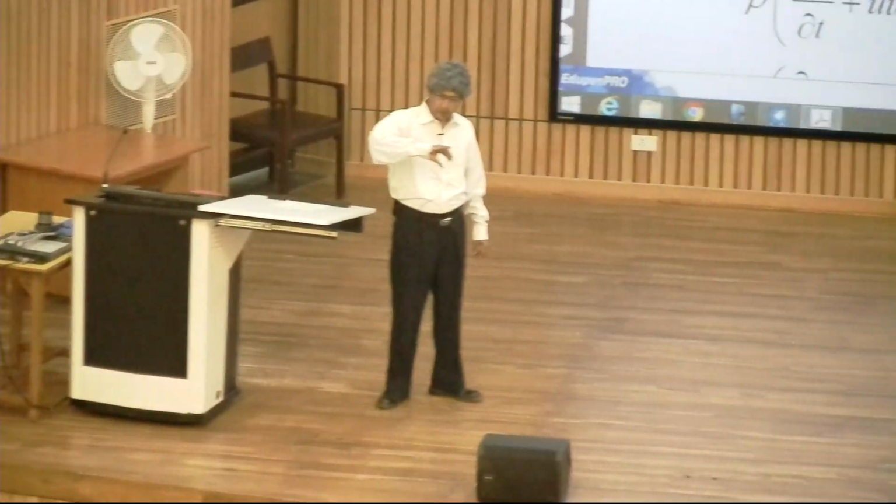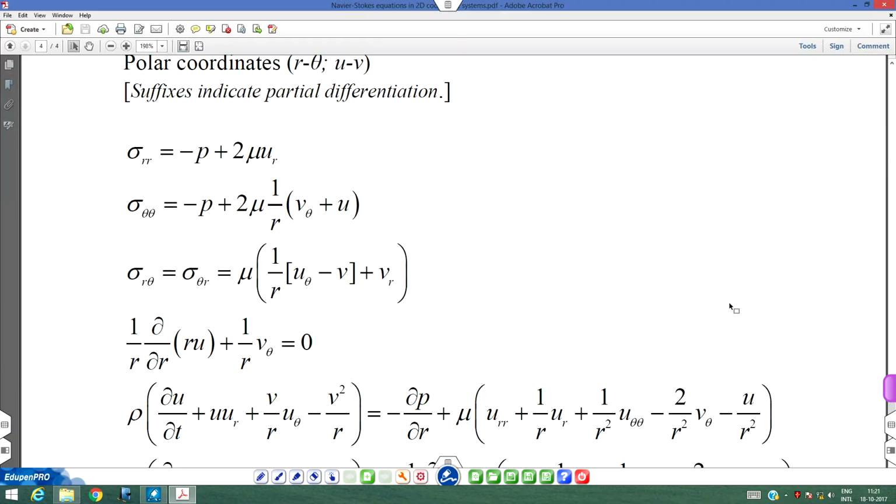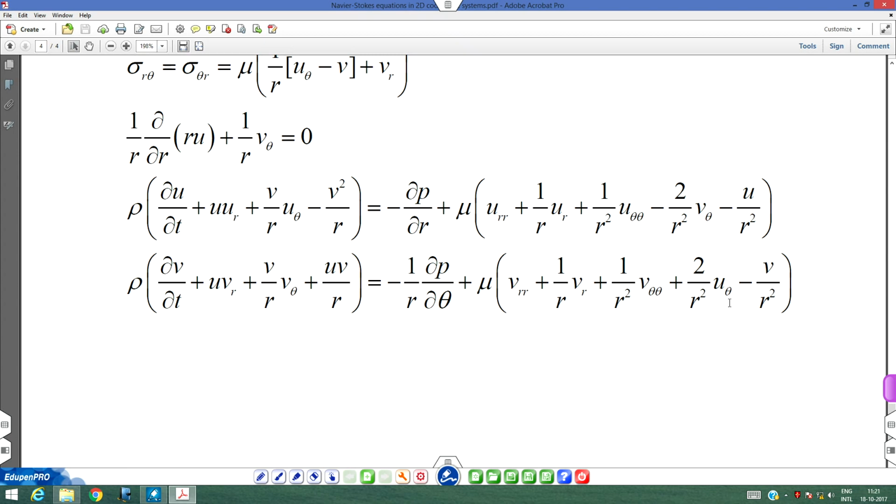So, if you force the fluid to rotate, you will generate a pressure gradient in the radial direction. This is similar to pressure gradient appearing in a gravity field where pressure is balanced by gravity. Here you do not have gravity, but you have centrifugal forces. The second equation: we also reasoned this derivative to be 0. u is 0, time derivative 0, derivative with theta 0.